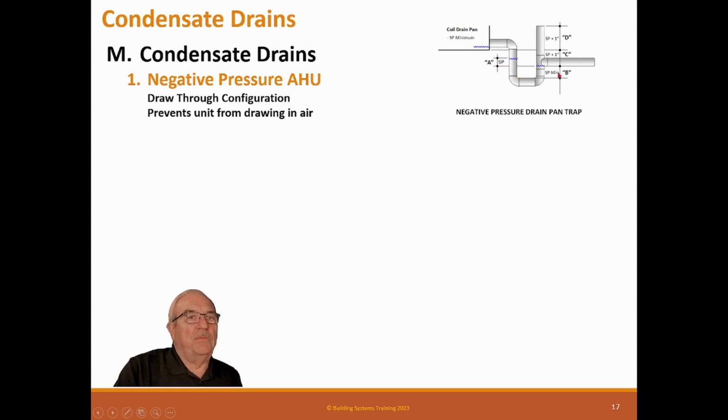So these dimensions are 1 greater than the negative static pressure of the unit. So you have to kind of know what static pressure is going to be in here before you can design one. And then some designers say we don't need a vent up here. We're going to close that off. We're not going to have one because the water will drain out of the unit. Well, it will, as long as the amount of water is not enough to fully fill the pipe.